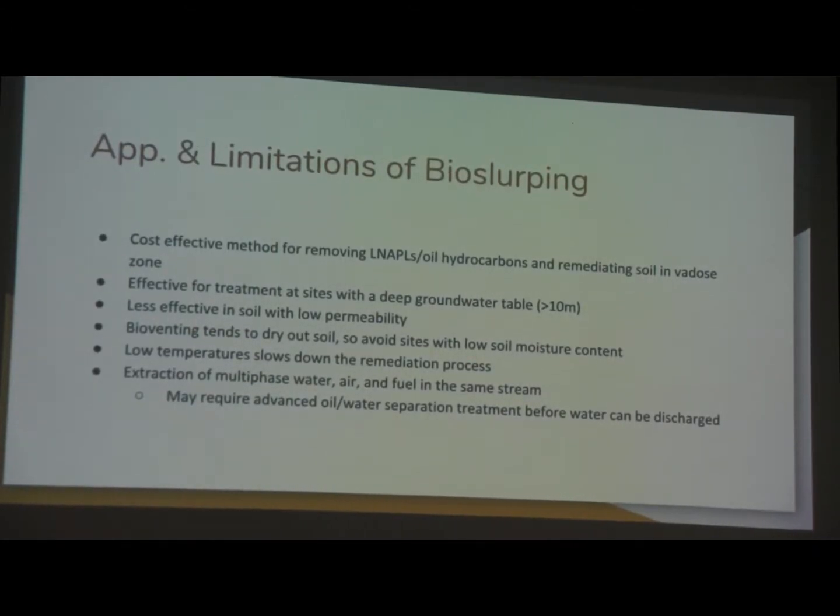So this technology is actually pretty cool because unlike the previous ones, we dealt with pumping air into the ground, and this one's more sucking the contaminant out, so it's kind of a little different. It is the most cost-effective method for removing LNAPLs and oil hydrocarbons. Also, it is really effective at deep water tables, as the other one was before, greater than 10 meters.